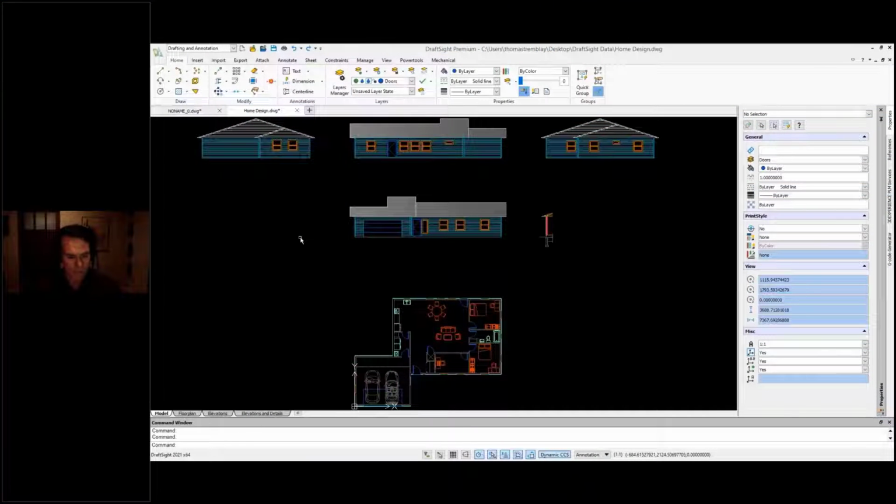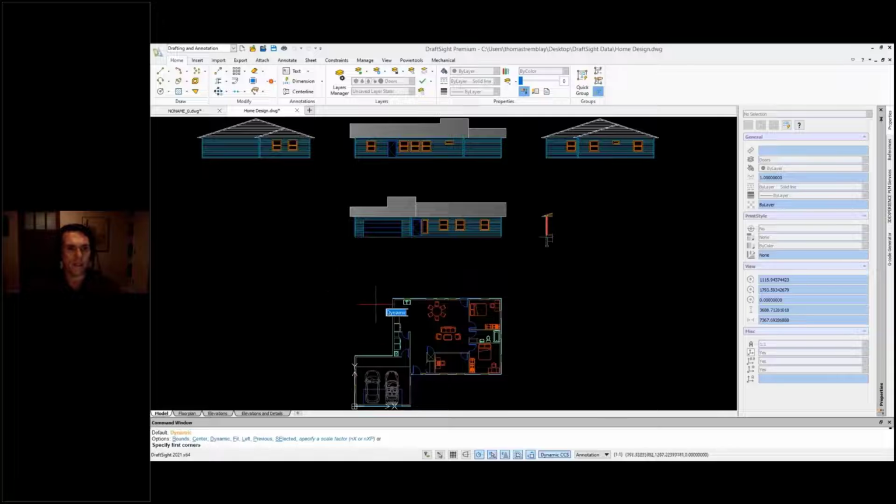Normally, I just type Z for zoom, and sure enough, it gives me the option right in the dialog of what tools begin with Z. If I came down to the command line, selected it, and started typing as well, it would give me that option right there. So I'll do Z, press enter, and it's ready to do a dynamic zoom, which you might be used to calling zoom window.